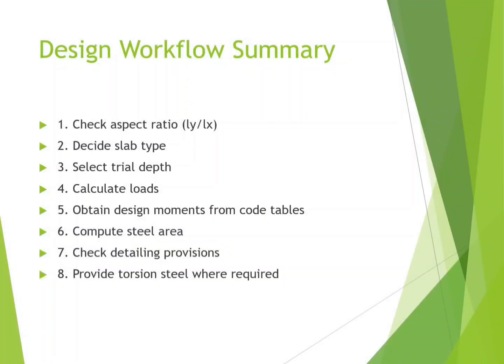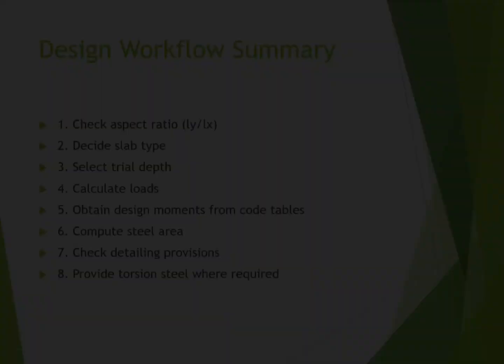To wrap it all up, check your aspect ratio first, choose your trial depth, pull your bending coefficients from the code tables, calculate your steel areas, and always run your final detailing checks.